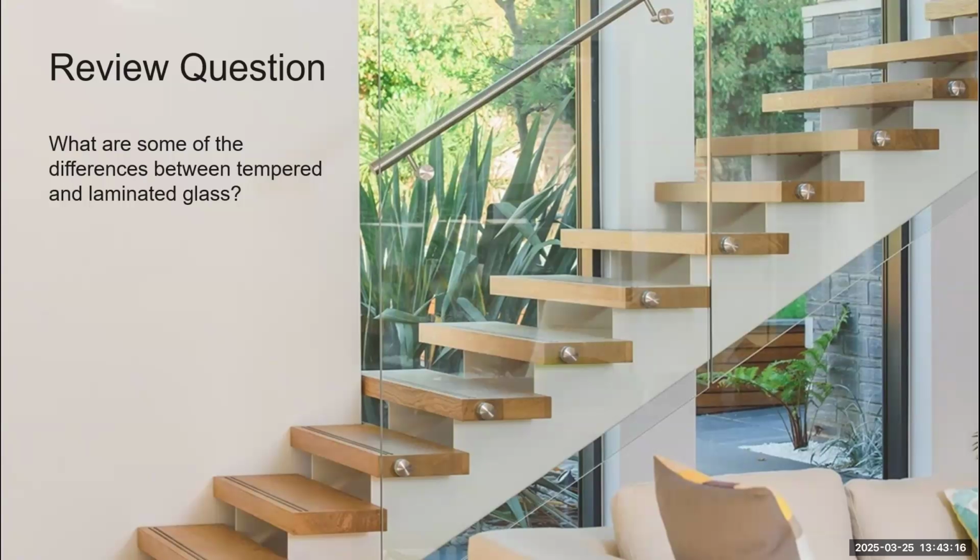Glass rail system at base of bleachers. Should the guardrail height be higher due to how one may trip forward? This is a tricky question, because ultimately you could say somebody could be standing on the seat, right? And there are certain requirements specific to stadiums themselves for additional strength in the guardrail, because there are additional loads that are put on and maintained onto the system for people leaning over. As far as heights, we have not seen typical higher heights required in that type of application, though.